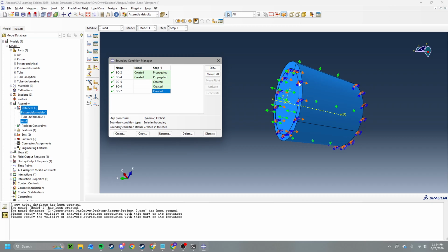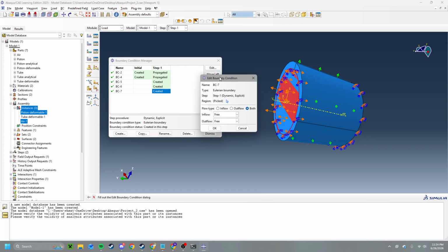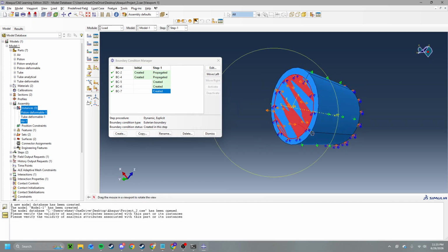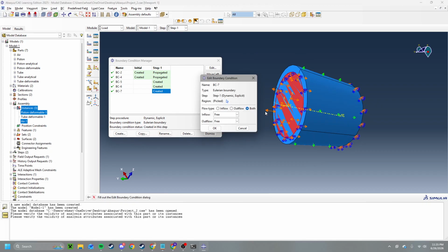And then for the top, if you don't set a different one for the top, it'll pull a vacuum. It'll make a lot of stresses that aren't realistic, because when you push it down, all the air from the environment is actually just going to go right in there, and it's not going to pull a vacuum. So I have free and free as opposed to none. And see, I picked this surface here. You can see it's Z clipping due to them being the same face.